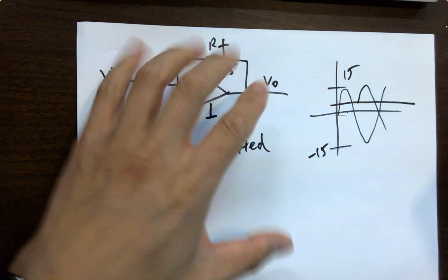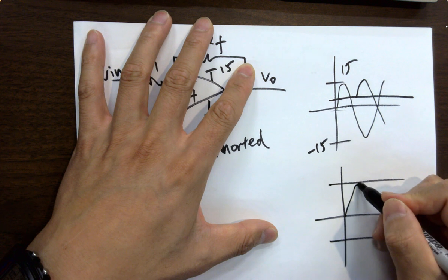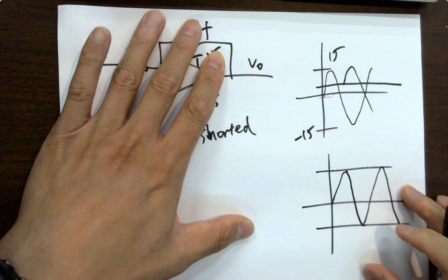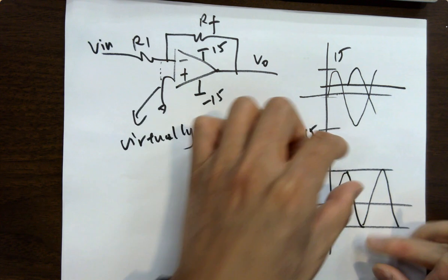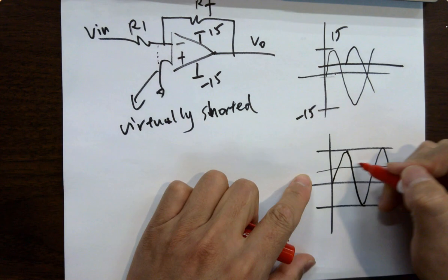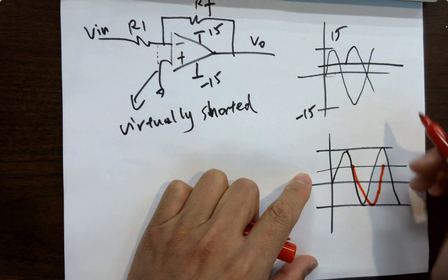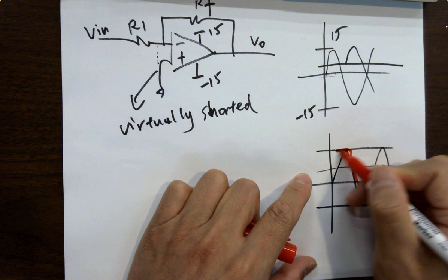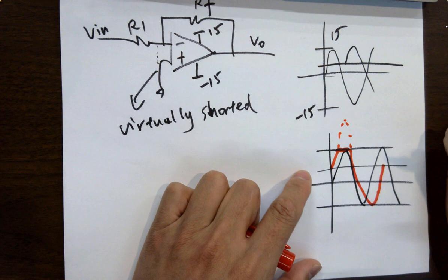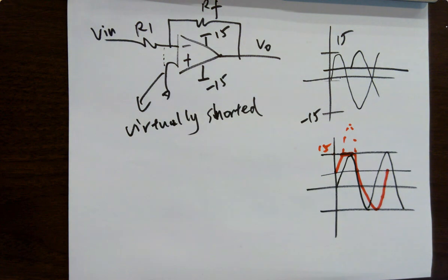Okay, that makes sense. So for example, if you swing a signal, let's say a sound wave, you can do it like this. You can amplify both sides in the same range. If you have the signal swing around this line, when you want to amplify it, definitely you can amplify the bottom part of it, but on the top it's going to saturate. It won't look like a sine wave anymore. It won't be able to go up like that because your 15 volts is right here. You don't have anything above 15 to provide to the signal.